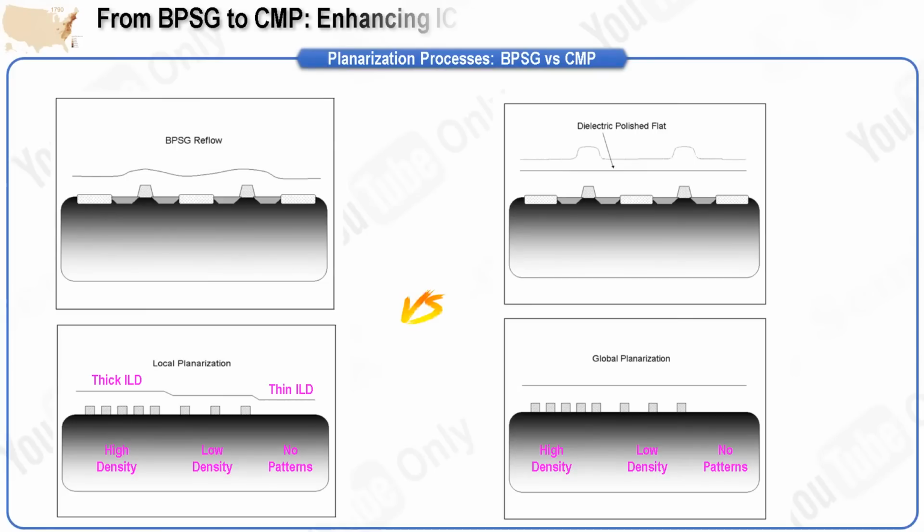In the late 1980s, IBM pioneered CMP primarily to facilitate the integration of multiple metal layers in integrated circuits. Originally known as chemical-mechanical planarization, it was developed specifically for achieving planarization rather than simple polishing. Planarization is crucial in the formation of metal layers during the interlayer process. For instance, in the transistor wiring process flow, after transistors are created on silicon substrates, a dielectric layer, often silicon oxide, is deposited. This layer, referred to as interlayer dielectric, ILD, or pre-metal dielectric, PMD, fills the gaps between gate and metal 1 layers, inheriting the surface's step height and sometimes exacerbating its topology.